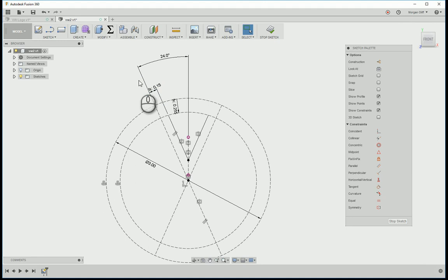So this is going to sit here, and then we can go ahead and draw alpha line again, here and here, constrain them symmetric about our projected line, and then parallel to one of these lines. And then we can also constrain that with this dimension. We can just hit dimension here.